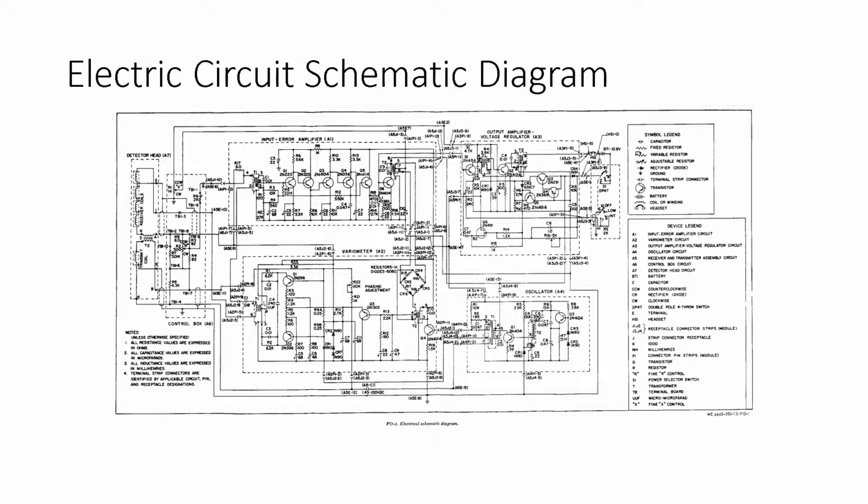Usually on the diagram too, there's two ways of doing piece parts. Let's say you're trying to buy a transistor from a very specific company because it has very specific properties that you're looking at. Sometimes you'll write that on the circuit diagram as the name of the transistor, but more often you'll use a reference designator. So let's give another example.